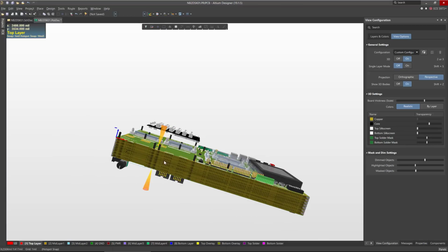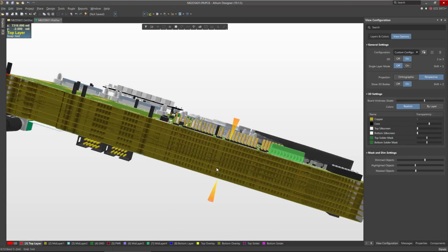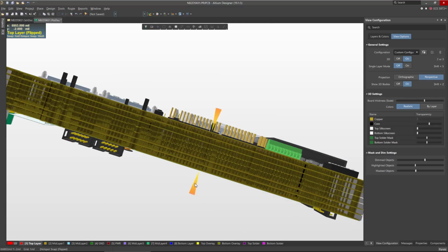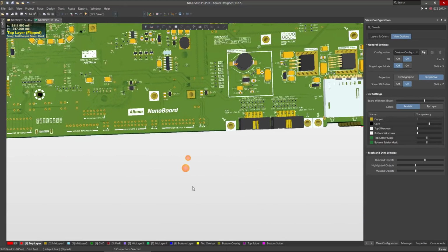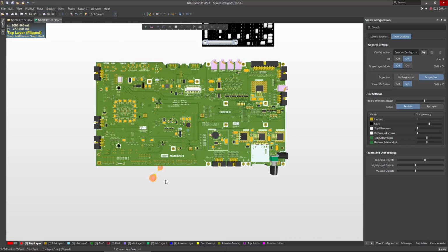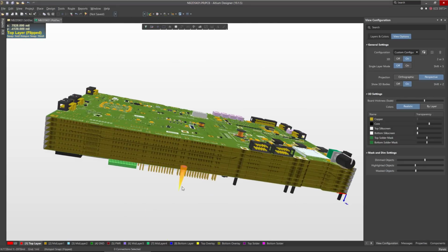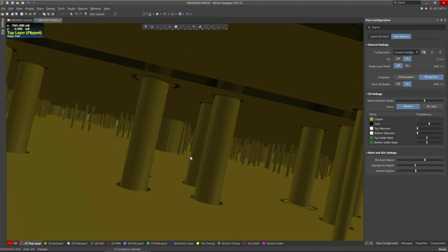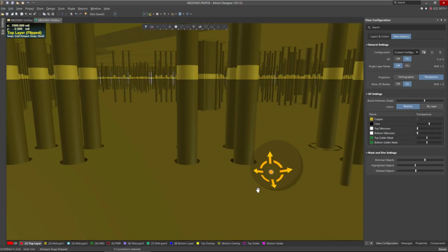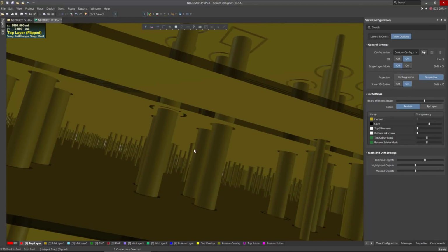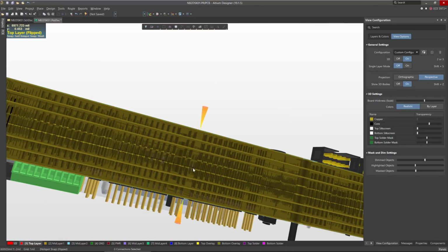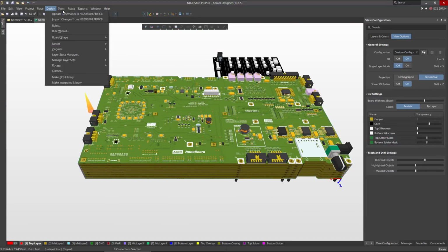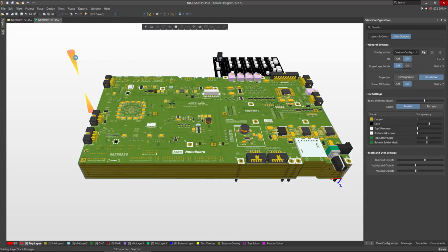And this is a big board, it's not a tiny board, and you are not trying to minimize the size of the board to use micro vias. So now let's take a look at the stack layer for this board. So by the way, you can go inside here, you can go inside and start looking into how these vias are connected, and it's very interesting how they make the 3D model in Altium Designer. So basically you can go to the design layer stack manager,